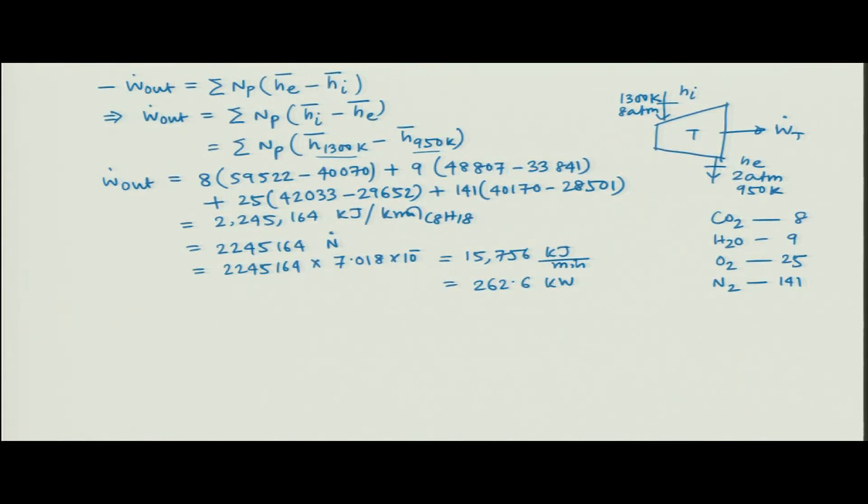We have to now calculate the entropy. Exergy destruction is nothing but T naught times entropy generation during the process. Now S dot gen we have to evaluate, and S dot gen can be evaluated from this expression.